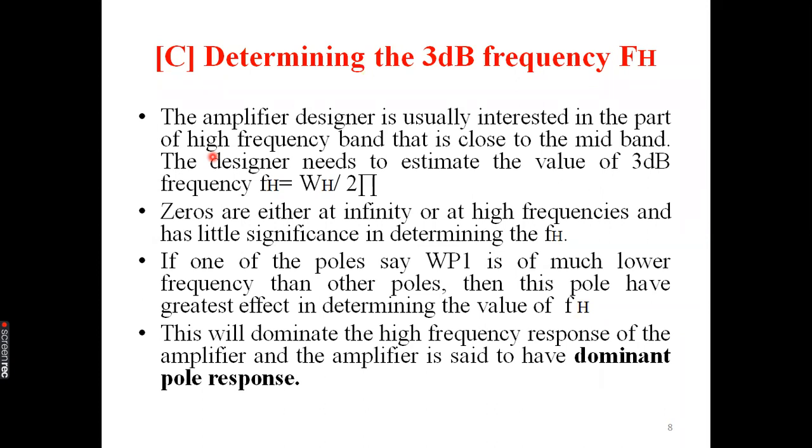Half power frequency means the frequency at which I am attaining 50% of the maximum power delivered to the load. Because till 49.999% it is fine, or else till 50.111% it is fine. Okay. Below that, it is not appreciable for me. I am giving some input power. I am getting some output power. But that output power should not fall below 50% of its maximum power. I am expecting maximum amplified power at the output across the load, right?